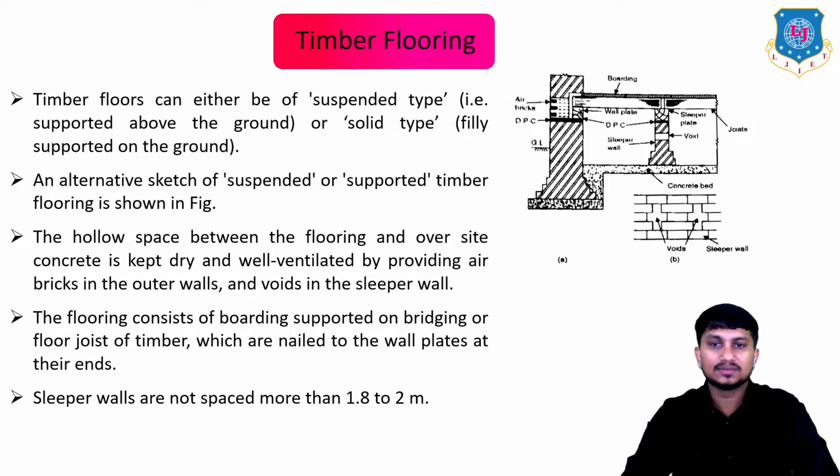The flooring consists of boarding supported on bridging or floor joist of timber, which are nailed to the wall plates at their ends. The sleeper walls are not spaced more than 1.8 to 2 meter. This is how the suspended timber flooring can be constructed.